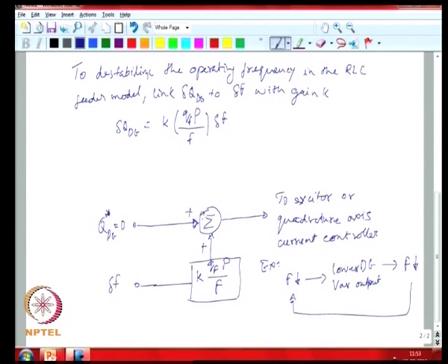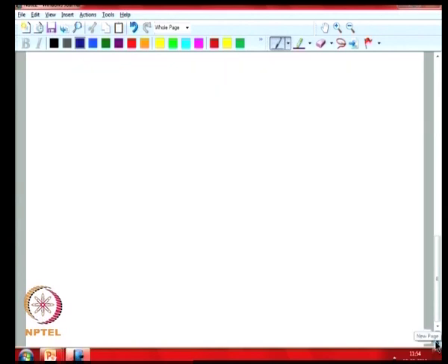One thing that you can see in this analysis that we did for your feeder along with the distributed DG source, in a case where you have unintentional islanding, and compare it with what you expect from a traditional power systems analysis book: in a traditional book, the link is between power and frequency and between voltage and reactive power.